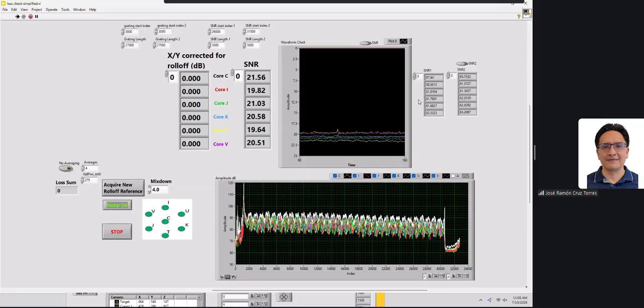But we did a good amount of thermal testing on this. I think it will be very similar for that, because everything in the system deflects when it comes to thermal drift: the lens holders, the actuator itself, the actuator mechanisms, the puck that's holding the sensor, your camera mounts, the camera itself. So it's really hard to nail down a single piece that you can individually track, because whatever system you're measuring these deflections with will also deflect if you put it in a thermal chamber.